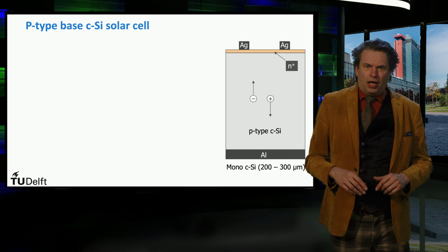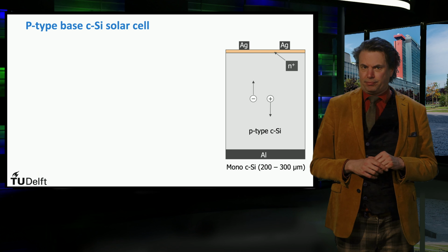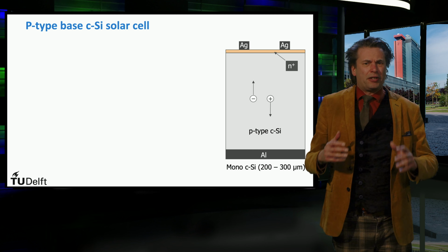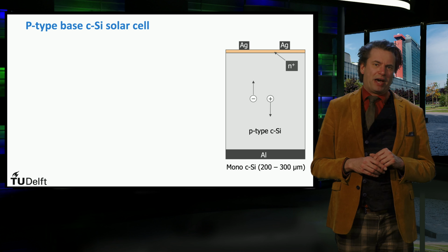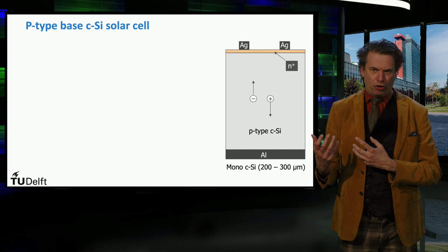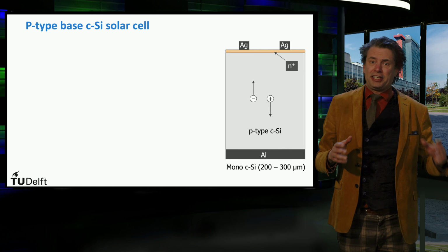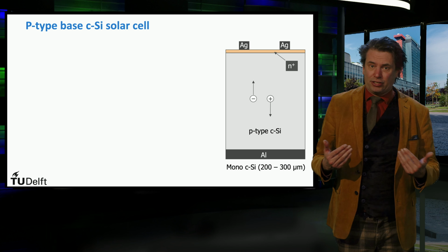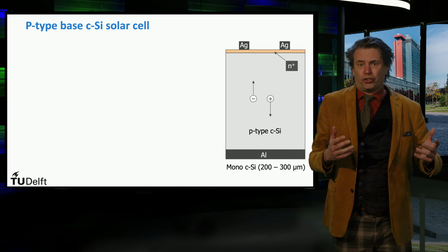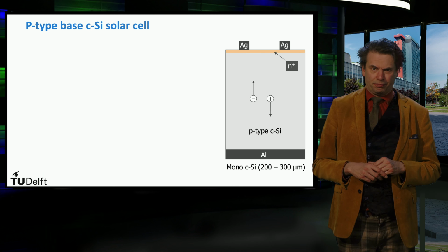First, last week we have discussed the importance of the high lifetimes of charge carriers. High lifetimes guarantee large open circuit voltages, or in other words, the best utilization of the bandgap energy. This means that we have to reduce the recombination losses as much as possible. In addition, recombination limits the collected current as well. Recombination in silicon occurs, as discussed earlier, through the Shockley-Read-Hall recombination and Auger recombination.